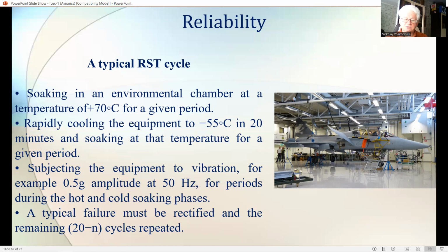The quality assurance, QA, aspects are very stringent during the manufacturing processes and very frequently call for what is referred to as reliability shakedown testing, or RST, before the equipment is accepted for delivery. RST is intended to duplicate the most severe environmental conditions to which the equipment would be subject, in order to try to eliminate the early failure phase of the equipment life cycle.